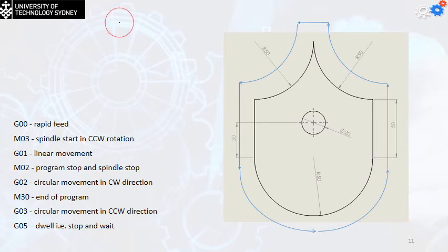So first, this is my cutting tool, a circle with the center point in the middle. Now the center point is very important for me because this will decide where I'm going to move my cutting tool. Always the center point will be moving along the tool path. The red line is always going to be in contact with the cutting path. So how to find my first point?